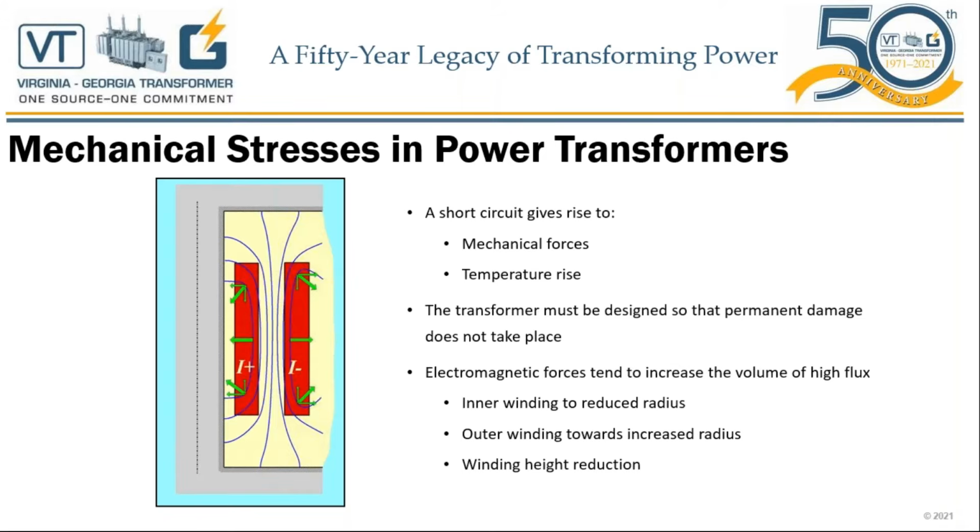The short circuit current, in a simple version, is the rated current divided by the impedance of the transformer. So if your transformer's impedance is 10%, which means 0.1, and your rated current of the winding is, say, 1000 amps, then your short circuit current, as simple as I can make it, there's more to it, but just for this webinar's purposes, is 1000 divided by 0.1.